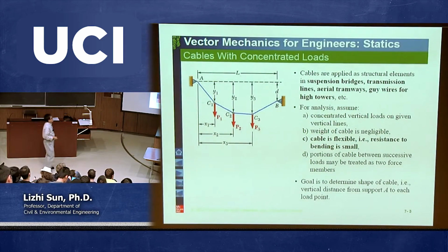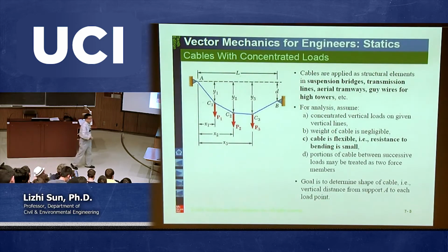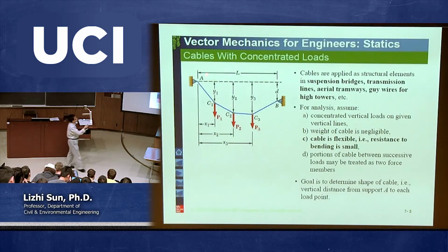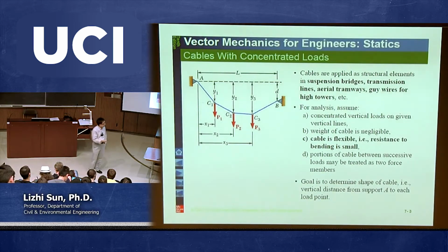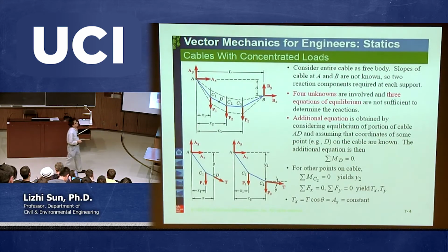Okay? So now, how are we going to calculate the reactions, and how are we going to calculate the cable force? Talking about the cable force, you're going to make some cut. But before that, we first need to calculate the reactions. And we know from chapter 4, chapter 6, chapter 7, how we calculate reactions. That's supposed to be simple. We just cut those reactions, right? We cut point A, we cut point B, and we plot the free body diagram. Okay? Let's follow what we have learned.